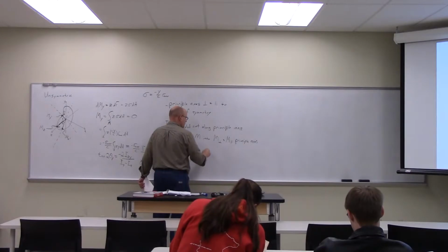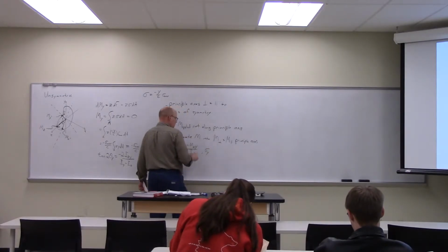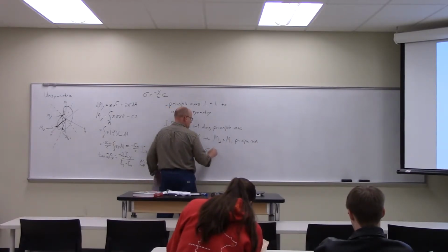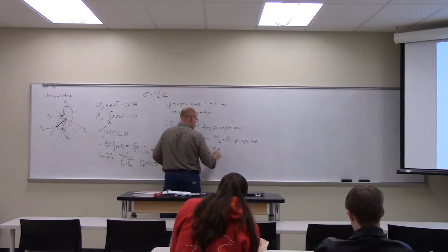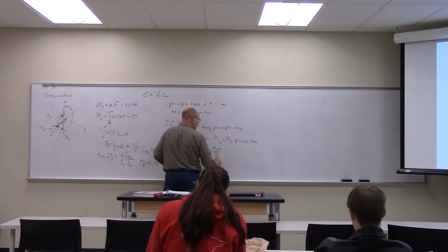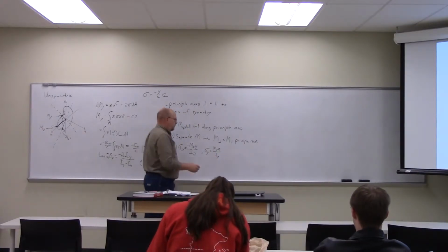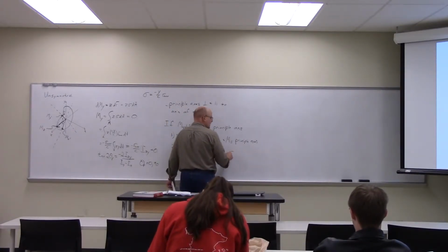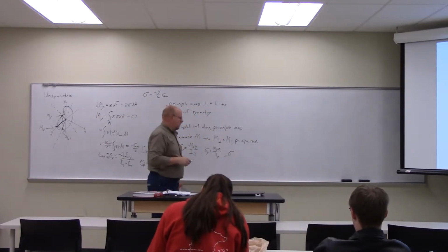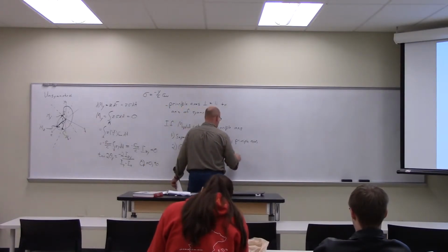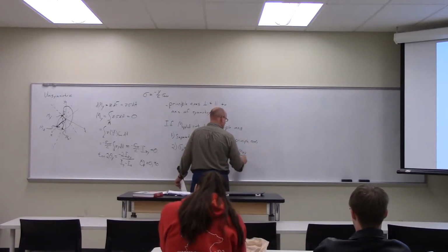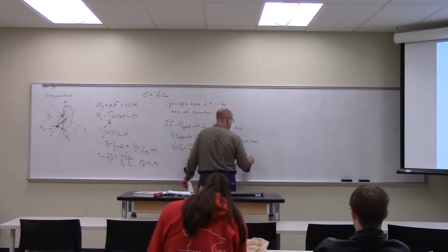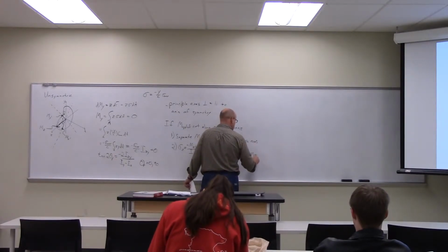And similarly, the stress caused by the y moment is M_y times z divided by I_y. So the total stress at any point in the cross section is going to be the sum of those two: negative M_z y over I_z plus M_y z over I_y.